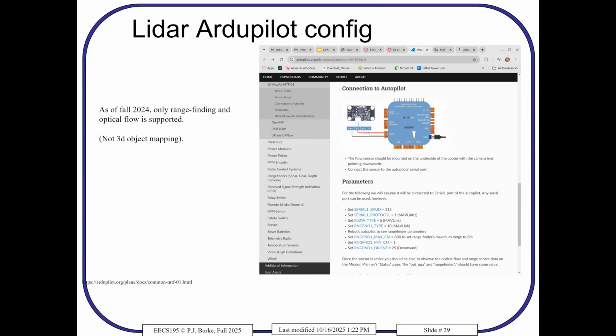So have they covered that in any of the courses you people have taken? So there are theory courses where they cover state estimation for not just drones, but any system where you have noisy inputs and you want to know a good average intelligent guess of what the actual state of the system is. So ArduPilot has that in there. So it intelligently uses different sensors, and you can tell it to trust certain sensors more in the settings.